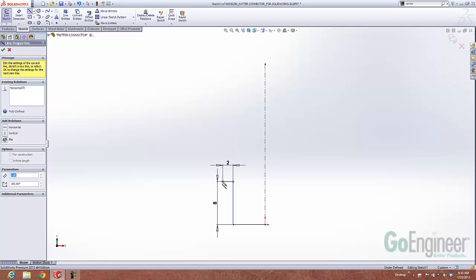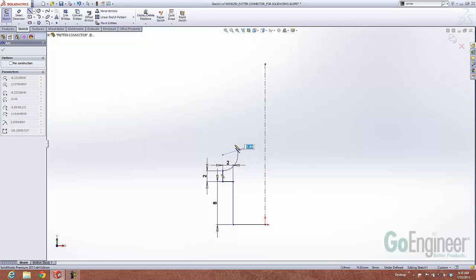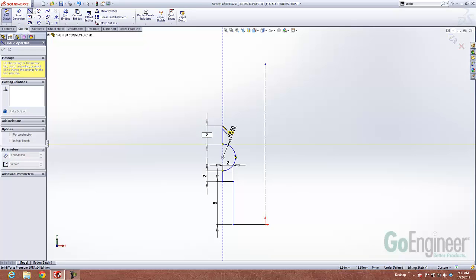This works very well, allowing me to very quickly come in and create my geometry and have it dimensioned. It works just as well with things like arc. So if I switch over to an arc, I can say that's going to be 2.5 for radius, and it'll create that, and I can just finish off where the arc is going to end. We'll go ahead and place that. We'll place a few more line segments here.